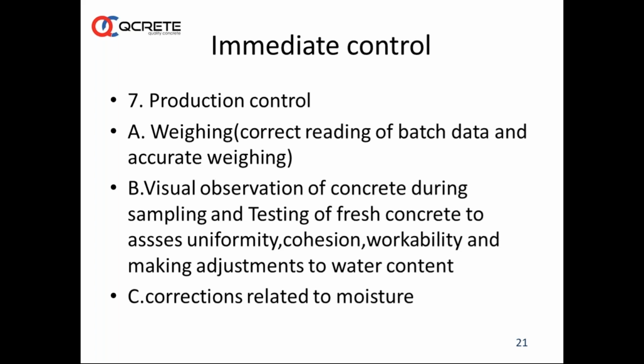Whether the exact weights have been weighed or not, which will be reflected in the batching data, we need to check. Visual observation of concrete during sampling and testing is for assessing uniformity, cohesion, and workability. And we sometimes need to make adjustments in water content.